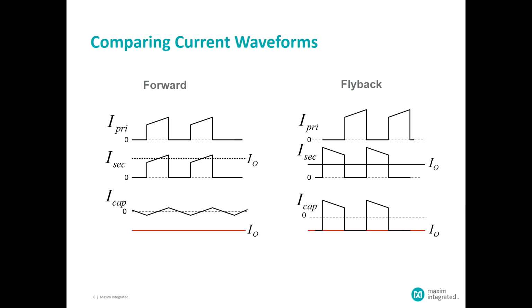And you see that in the capacitor current waveforms down on the bottom right, where the capacitor current, when the secondary current is flowing, gets all that current into the capacitor, which is above the zero reference point. And then when the primary side is conducting and there's no current in the secondary, the current in the capacitor is a negative constant current because the output voltage is constant coming out of the capacitor.